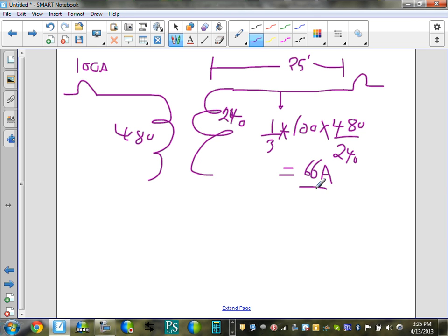Okay, so what size conductor? Can you guys find a conductor under 66 amps? That would be number 8, more than number 8. Number 4? That would be your number 4 conductor, under the 75-degree column. How much current can number 4 carry under normal operating condition, 75? 85. Okay, then you can go up to 85, so this cannot be more than 80. That circuit breaker cannot be more than 80 amps, to limit the current to the capability of that conductor.